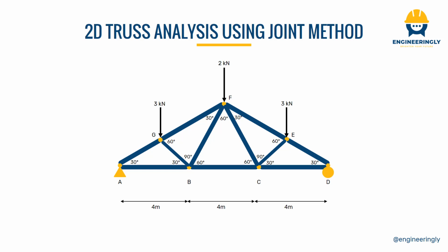For example, assume that you have a span of 50 meters. If you're going to cover that with concrete beams or any other type of concrete structural elements, it will be heavier, and in some cases it will not be feasible. If you go to the big stadiums or maybe halls, the structures are covered using two-dimensional and three-dimensional trusses.